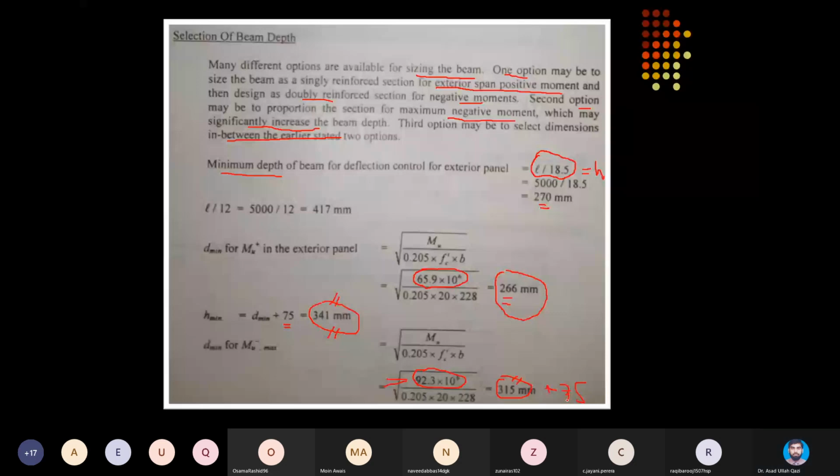Before I start working on the design, there are few important decisions which are made here on this slide, and then onward we will be designing the beam sections, and it's just repetition of what you have studied under the T-beam behavior, under the T-beam design article, that in monolithic construction, when you pour the beam and slab and you are integrating the slabs with the beams, the question will be how much part of the slab will be considered as integral part of the beam.